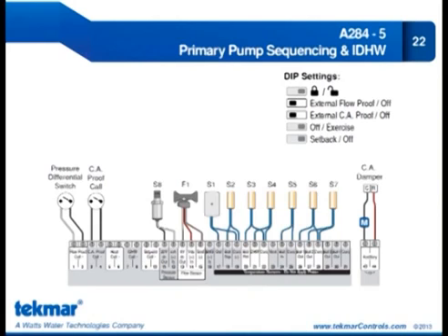But a lot of these you can translate from BACnet to that. That's correct. There are third-party devices out there where you can buy a gateway, such as FieldServer. They make these third-party gateways, so they'll take information from one protocol and communicate out to a different protocol. So let's just say your customer is working on a job and they require, say, LonTalk, for example, then you can purchase a FieldServer gateway aftermarket and then integrate it with this. That answers the question. Okay.